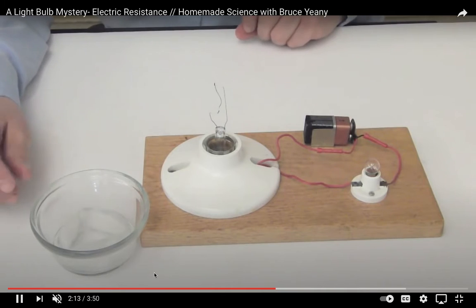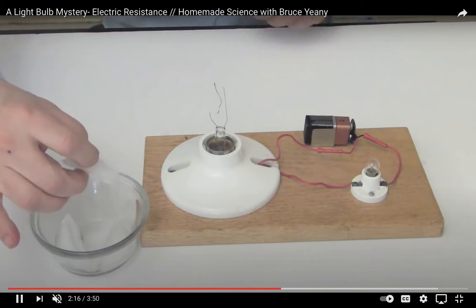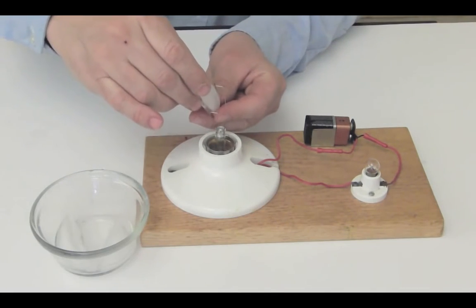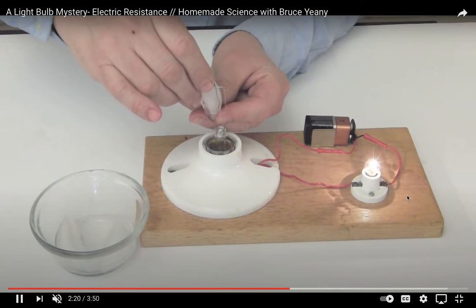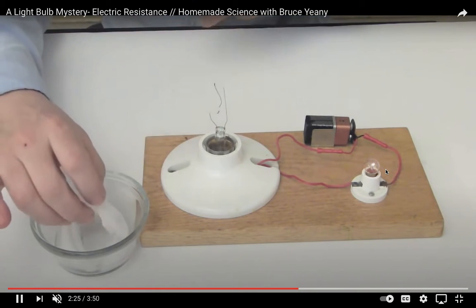Now, the same thing happens again if he takes an ice cube and puts this on the filament, that's going to result in a drastic decrease in temperature inside of the filament, and as a result, it's going to result in a drastic decrease in resistance inside of the filament. And as a result, the current is going to skyrocket inside of our circuit, resulting in this extremely bright output of light and thermal energy.